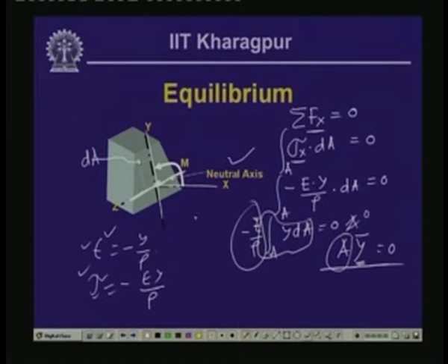that is the reason this particular axis is termed the neutral axis. So, in the cross section we have a point where the strain and the stress are 0, and it varies linearly over the entire depth of the beam. We will have a variation something like this, wherein we have zero strain or zero stress over here, and here we will have the strain and the corresponding stresses. This gives us the variation of the strain and the stress.